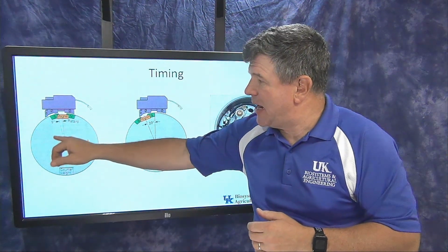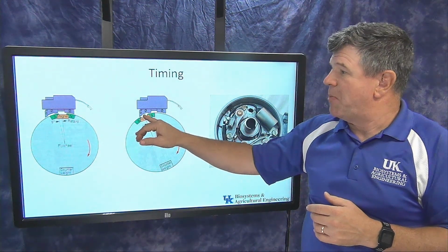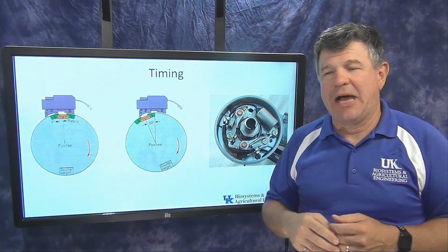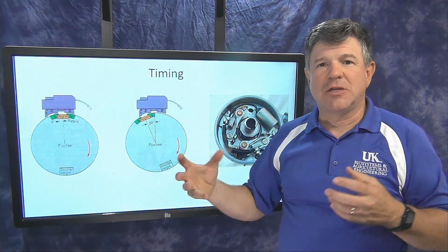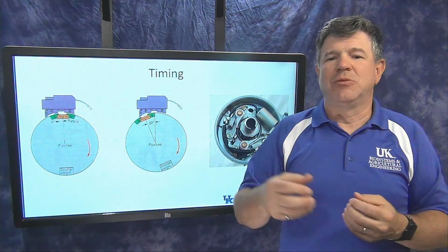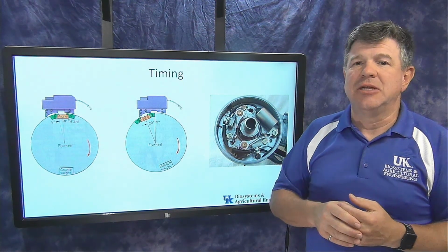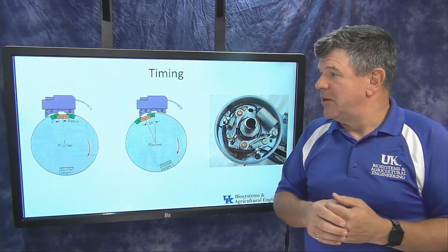A lot of that can happen naturally in a magneto type engine, just because of the magnets rotating faster past the coils. That will actually change the time at which those sparks, those big voltage spikes, happen. So that will change the timing of when that happens up there.